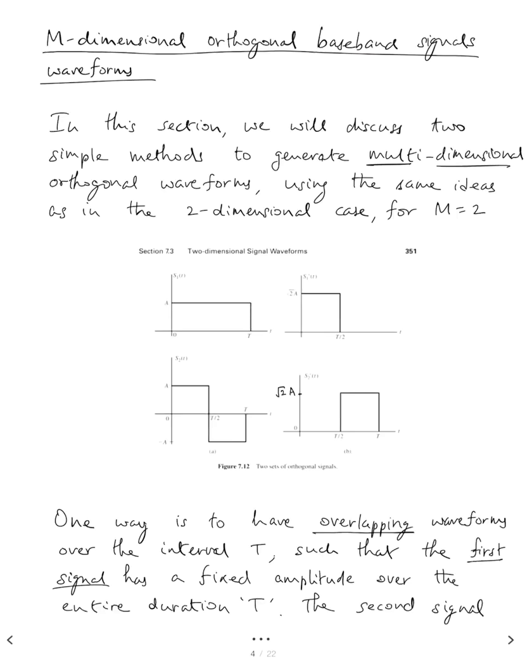So let us have a quick recap of what we did previously. Previously we saw some baseband representations of 2-dimensional orthogonal waveforms. So we had the first representation here of signals S1 and S2 of t, which are orthogonal to each other. How do we know they are orthogonal? Simply compute the inner product, the integral of S1 of t into S2 of t integrated over the interval 0 to T. You will get it as 0, so therefore they are orthogonal to each other.